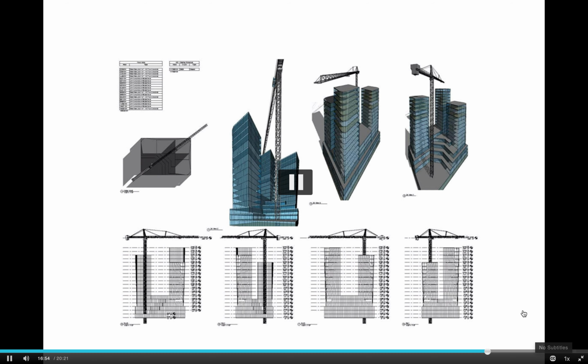If we go back to that first slide that shows that really tight building location where you have adjacent buildings behind you and to your left and your right, you only have one location to pick from, and you don't have any locations to really have storage. Even if you build a sidewalk shed there, that really doesn't afford you the capacity to store a lot of members on top of it to be able to pick from. So you'd basically be trucking in whatever you need picked.